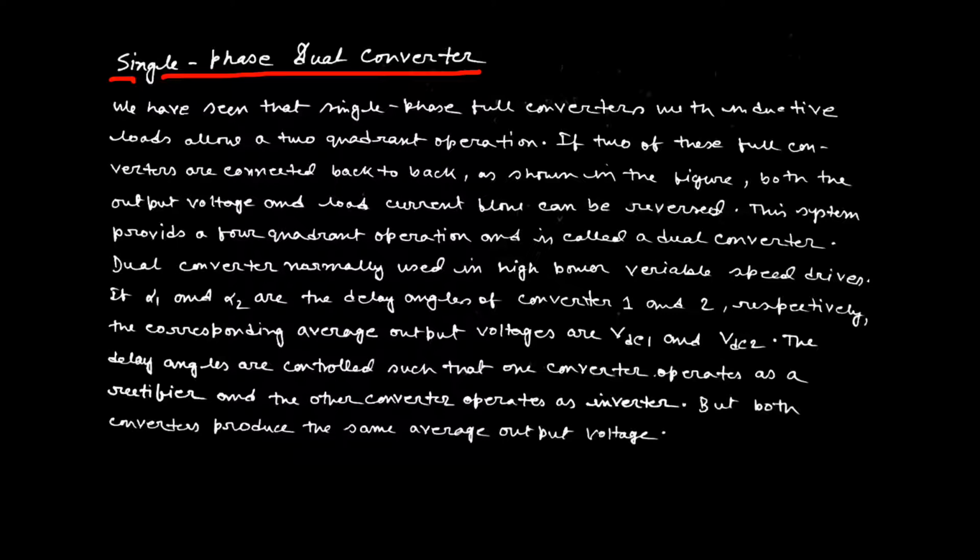In case of 4th quadrant operation, when the inductor starts discharging, it will cover the 4th quadrant operation in which the current is still in positive direction but the voltage appearing across the load is in reverse direction. That is why in the first quadrant operation the power is transmitted from supply to load, and in the 4th quadrant operation the power is delivered from load to supply.